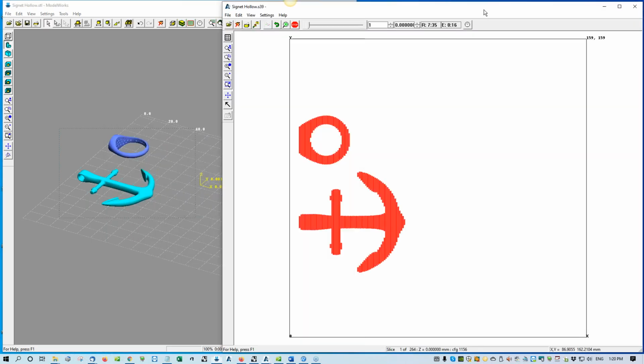The analyzer is the piece of software that allows us to see each layer as it will be printed on the printer build plate. So you can see two models. I can magnify it if I want to, or zoom it back. And this is the first layer. So the first layer will be just support. The red material is the support wax. It will be melted away, and Matt is going to talk about that.